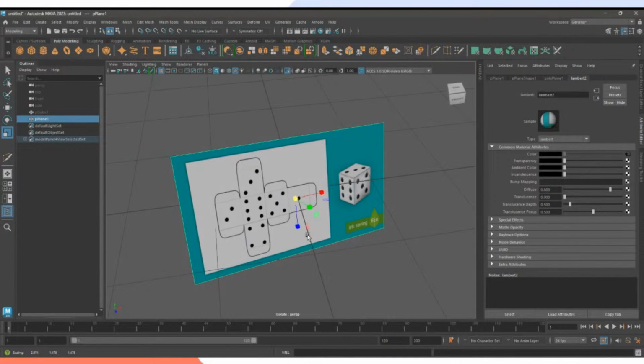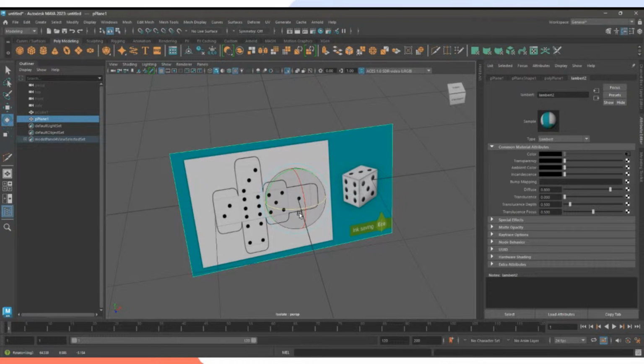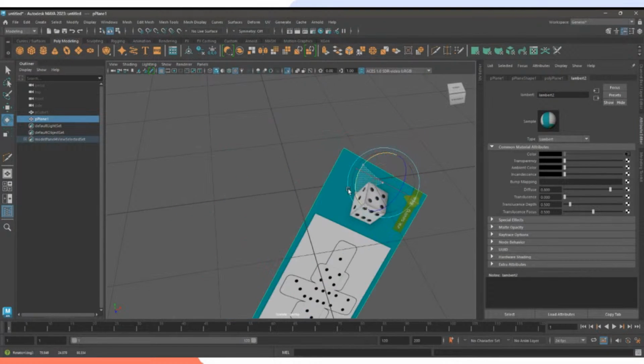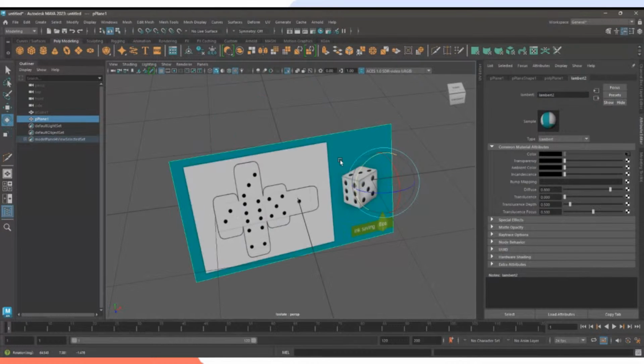And you can see the axis. We call this the axis. It sometimes can follow your object, sometimes it doesn't. You can do this by holding the D key, and you can move the axis from one part to the other. For example, there, and you can control that part as well. If for some reason you have done this by accident, here's a tip. You can hold the D key and then hold right click, and then you can press reset pivot.